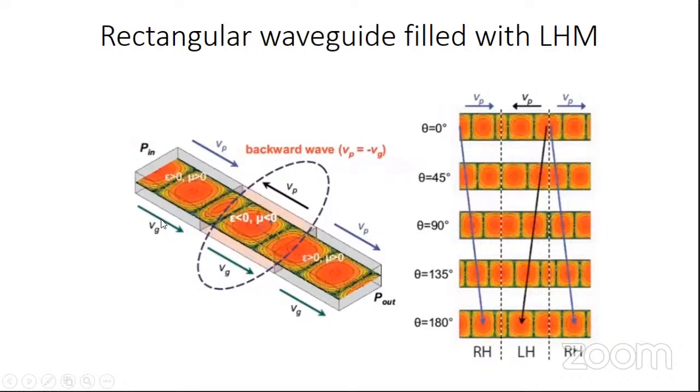What does this property do to the phase velocity and group velocity? You know both the phase and group velocities with respect to the rectangular waveguide, but these material properties affect the phase velocity but not the group velocity. You have to keep this in mind. Only the phase velocities will change, not the group velocities, as the phase of the wave is changing.